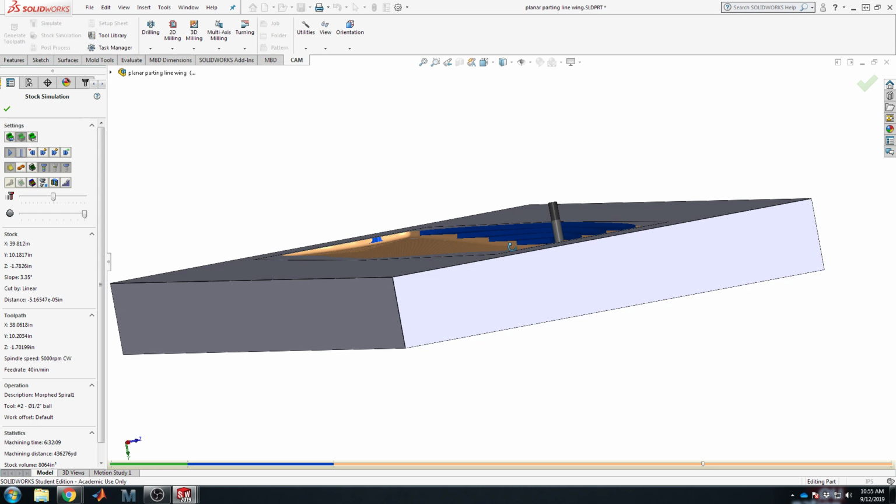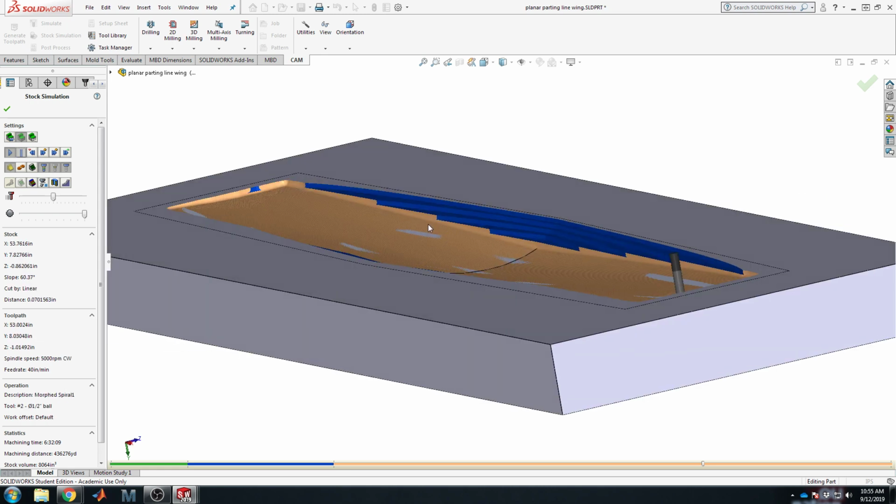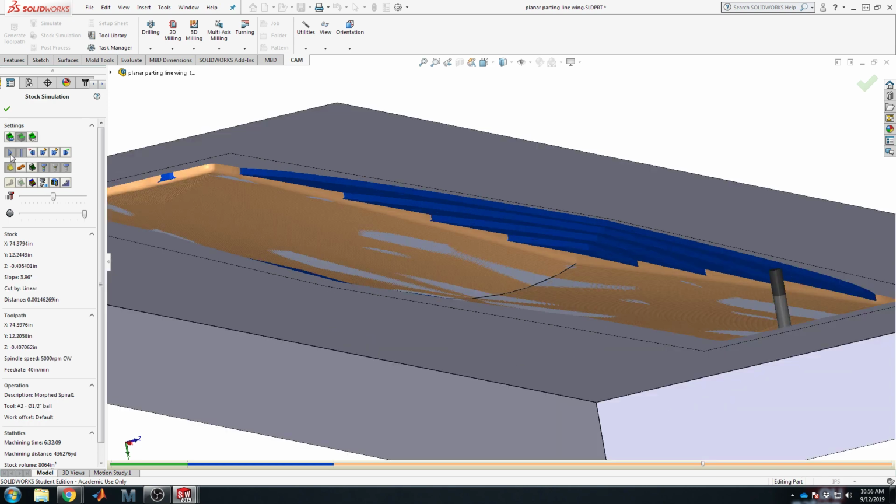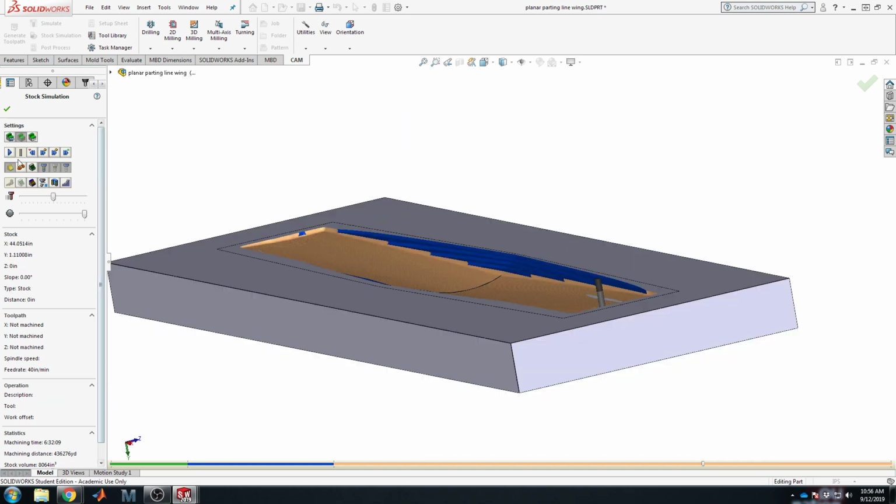And I'll pause it for a moment to show you the benefits of doing this roughing pass. Notice that really that ball mill is only having to cut through, maybe I'd estimated, a 1/2 inch of material. As soon as the depth is getting too high, well, there the next pass of roughing was taken to alleviate load on the cutter head. So this kind of stepped pyramidal, inverted pyramid look really helps reduce load on the ball mill. Well, let's finish this, let it finish the simulation.